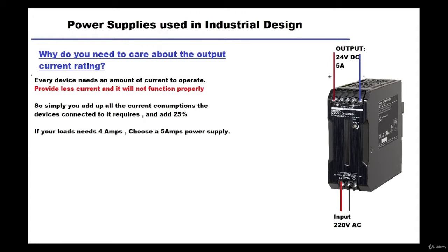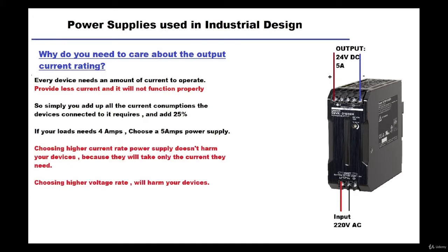And since any device will consume more current in the first few milliseconds or few hundred milliseconds of its operation, we need to put in a margin that this power supply can handle without the device failing at startup. And usually the nominal value that we choose is an additional 25% of the total current that we need. Now here's an important note.